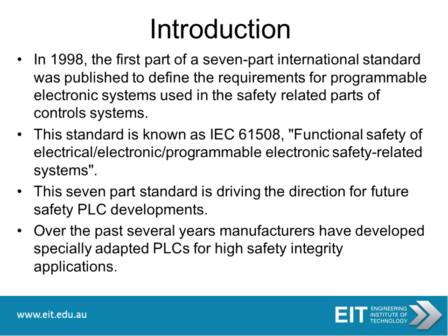Now, in 1998, the first part of a 7-part international standard was published to define the requirements for programmable electronic systems used in safety-related parts of control systems. This standard was known as IEC 61508, Functional Safety of Electrical, Electronic, Programmable Electronic Safety-Related Systems.